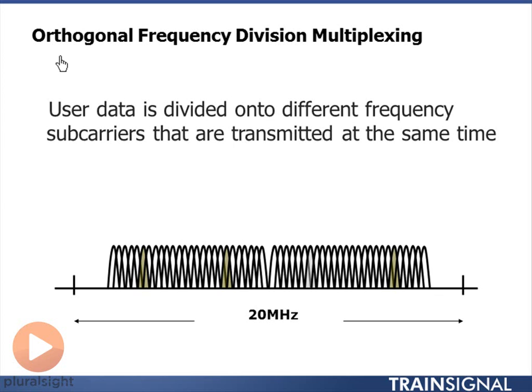The secret of this technology is that it's orthogonal, and you'll see here how the signals overlap with one another, and see how this signal here is a null while this one peaks. That's the property of orthogonality. So I can literally get the signals to overlap and not interfere with each other, which means I can get lots of subcarriers really close together, and that means I can get up to super high data rates. So we've talked about direct sequence and spread spectrum, and this is orthogonal frequency division multiplexing, just different ways of transmitting over the frequency channel.